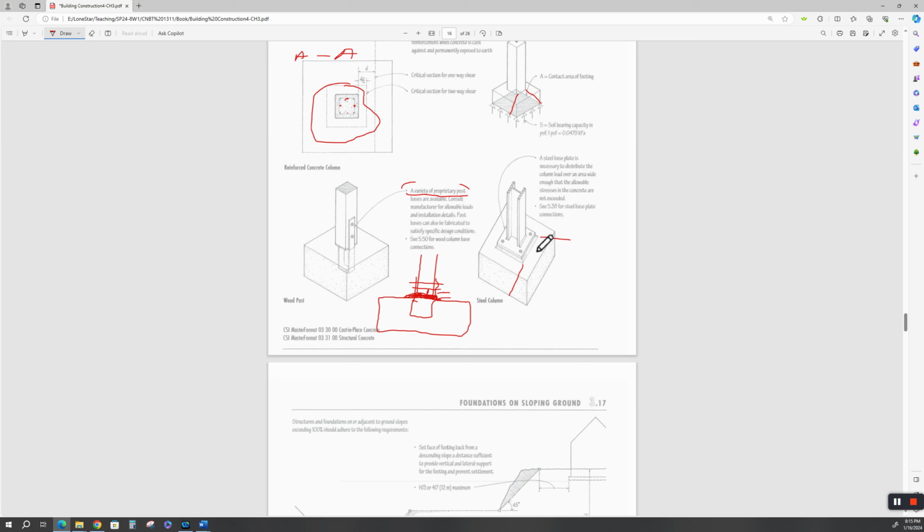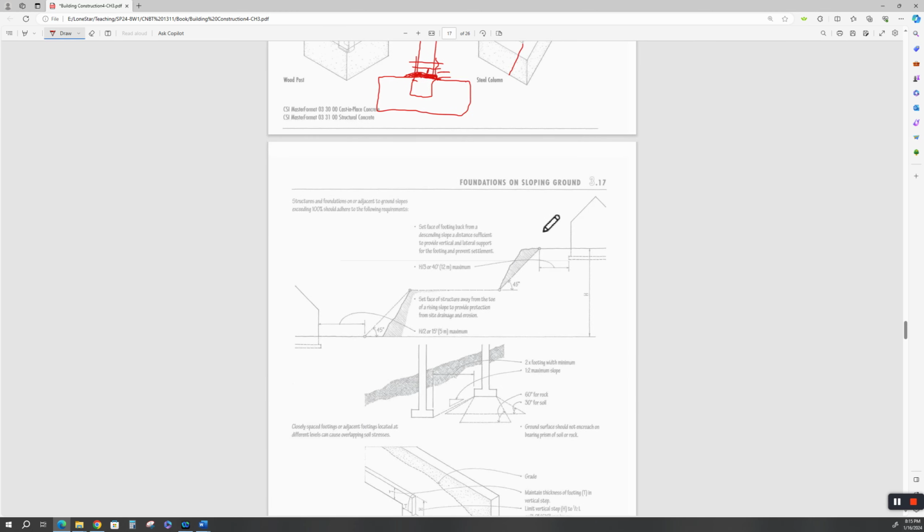They're grouted with a non-shrink structural grout, which is a whole lot different than regular cement. It's not grout that you'd use for tile. It's a non-shrink, expansive structural grout.